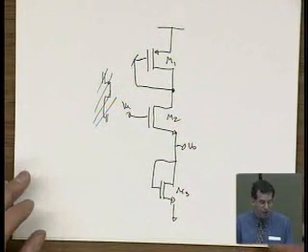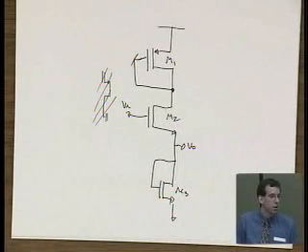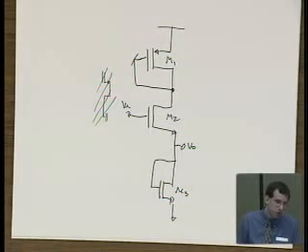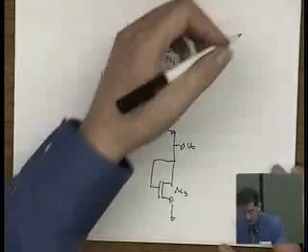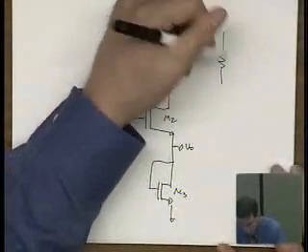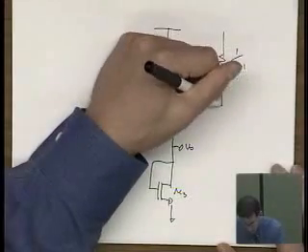Okay, and when I look at this, I see shortcuts. There are 3 transistors here. 3 transistor circuits are kind of difficult to analyze. Can we reduce anything? What can we reduce? Right, we have 2 diode connected transistors. So we can replace this guy with its effective resistance, which is 1 over gm1.